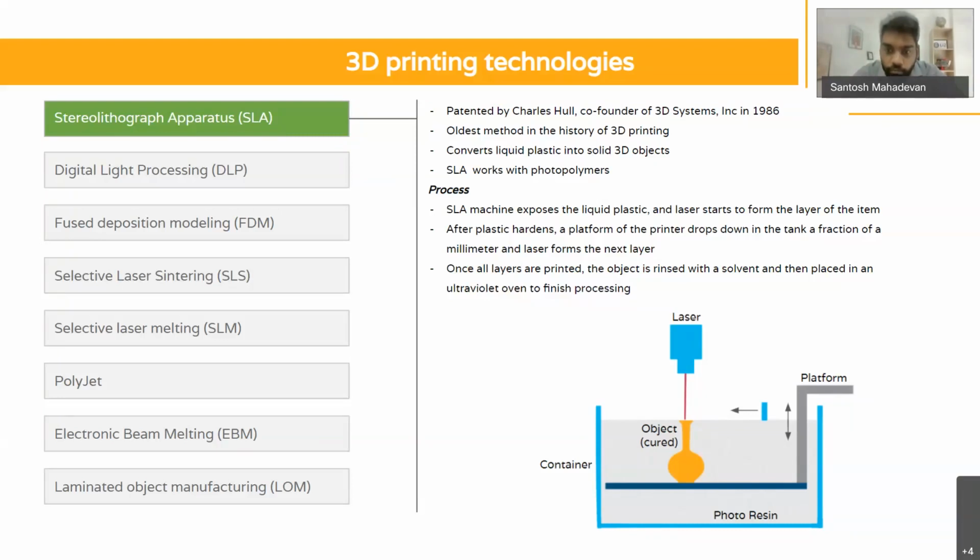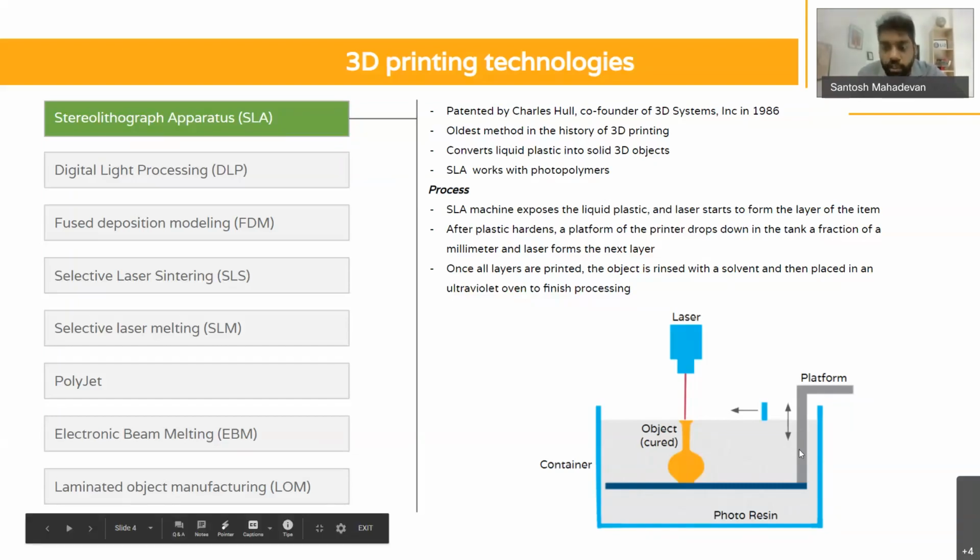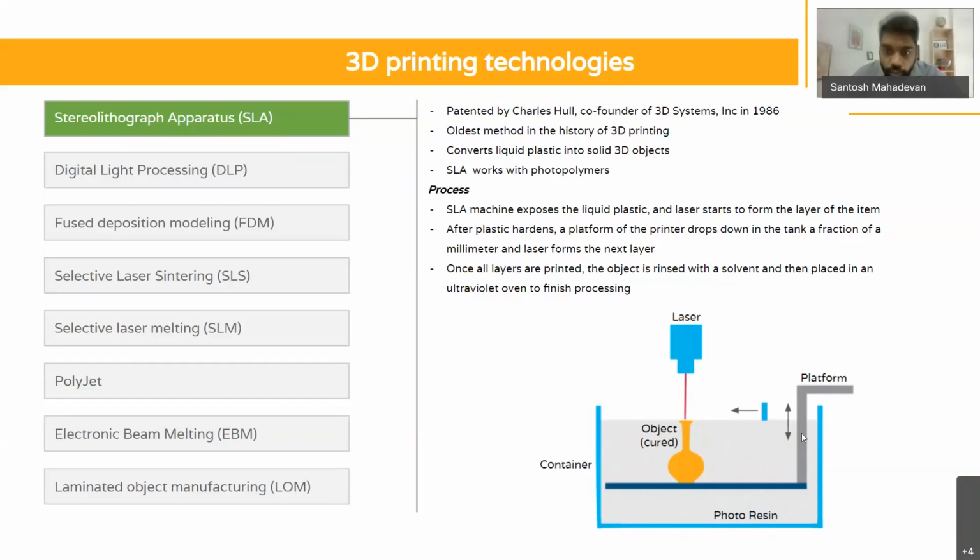Once this square of 1 height, 25 across length, 25 across width is done, the platform moves down by 1, and the process is repeated. As you guessed, the position of the next layer will coincide with the position of the previous layer. So one layer literally gets formed on the next layer, and on top of that, and on top of that. So this platform moves down 25 times to give you the 25 layers that are going to be formed on that cube.